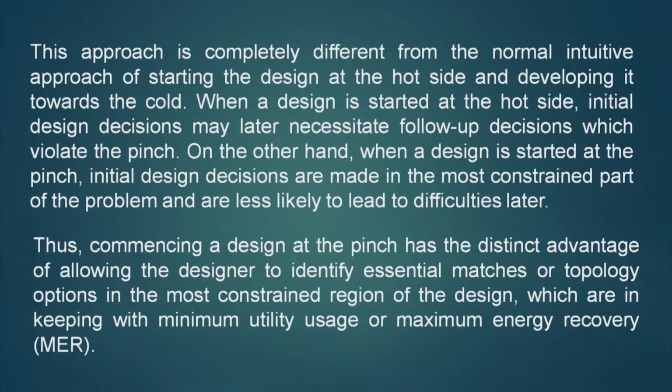The maximum energy recovery design will only take place when no heat passes through the pinch. If heat passes through the pinch, we cannot call it a maximum energy recovery design. And in a maximum energy recovery design, the requirements of utilities, which consist of hot utilities and cold utilities, are minimum.